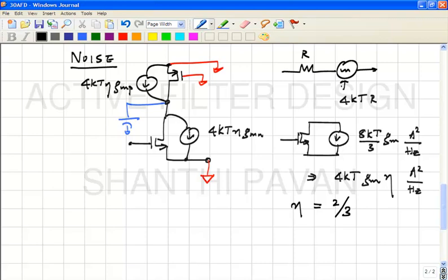All right. So if I think of this as a transconductor with a transconductance GMN, please note that in the incremental equivalent, it is only the NMOS transistor which is being excited by the input voltage. So the incremental signal current coming out is simply GMN times VD, right.